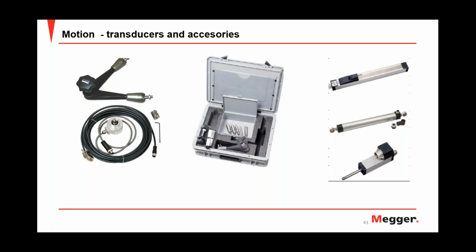Analog or digital transducers with different ways to measure the motion. You can have rotary or linear transducers. Of course, you need different ways to install those transducers in an appropriate way to limit the possibility to have any damage during the operation. Hence why a flexible mounting kit is useful. Some circuit breaker manufacturers are implementing transducers as default in their circuit breakers, but that is more or less uncommon.